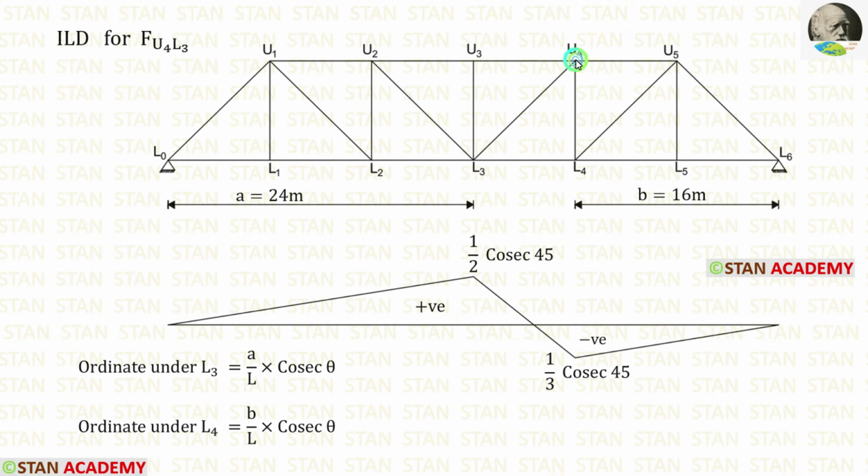In the same way, we can draw the influence line diagram for the force U4 L3. Project the points L3 and U4. Then draw a line in the opposite direction of U4 L3. Then we can apply the formulas for the ordinates.